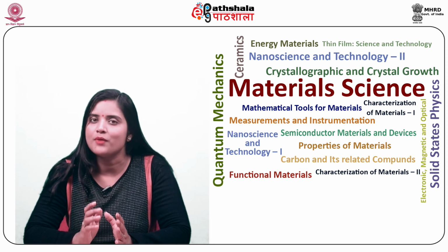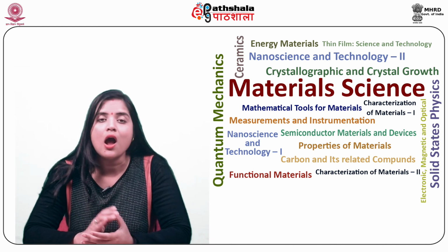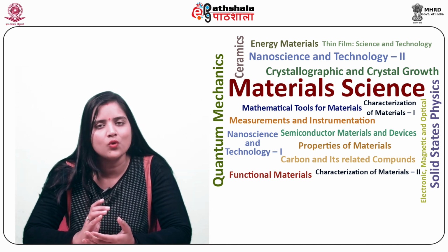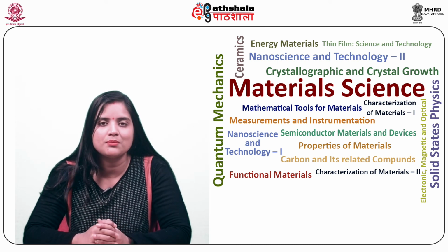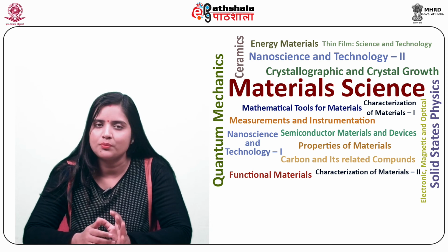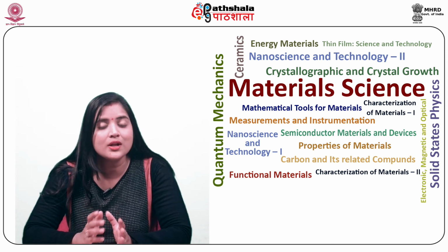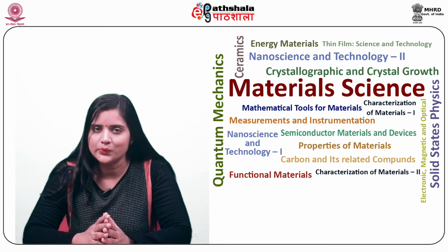In the 4-probe method, contact and spreading resistances are very low with voltage probes, and hence accuracy in measurement is usually very high. To measure very low resistance values, the 4-probe method is used.